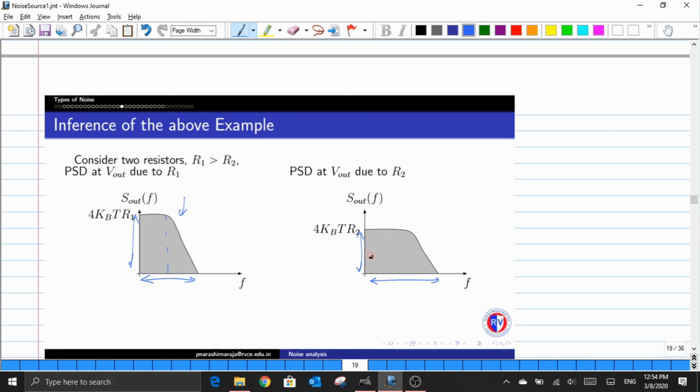and clearly one can see that when we perform an integral over this power spectral density at the output of the RC network, which is nothing but the computation of area under these graphs, the area remains the same, and that area value is given by the Boltzmann constant times the temperature divided by the capacitive element.